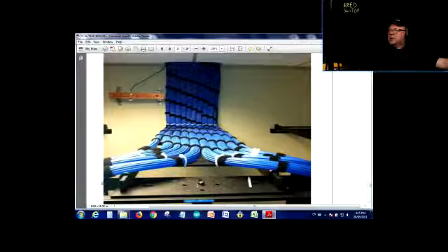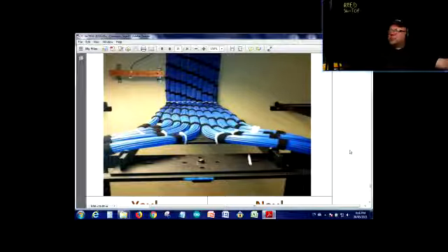Another one here, that's a good one, right? That's a lot of wires. They look to me like Cat6 wires, and you see lots of Velcro being used, and some other straps, but no zip ties, because if you use zip ties on category or Ethernet cable, you are compromising the structure by squeezing the wire. And once you squeeze the wire, you are altering the physical parameters of that wire, which means you're altering the specifications of that wire. So Velcro is the key. That is a good installation and takes a lot of experience, knowledge, skill and time to do.